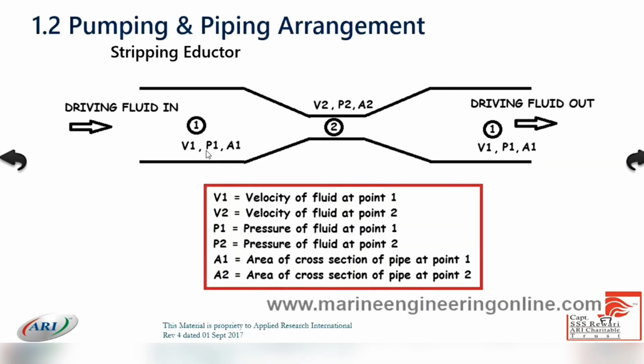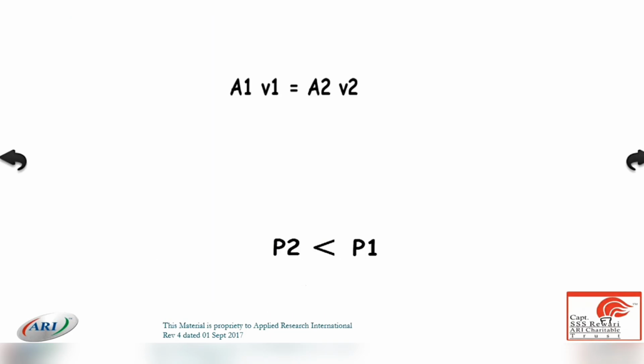Okay, these are the pipelines, and other than this, you have the crude oil washing line, you have the MARPOL line. Crude oil washing lines are used for crude oil washing the tank. The crude oil washing line can also be used for tank cleaning, and MARPOL lines are used for discharging the last bit of cargo after draining, so that all the pipelines can be drained, all the pumps can be drained, and the last bit can also be discharged as shown. And the main stripping system is used as an eductor on most of the ships. So these are the pipelines which are used on ships.